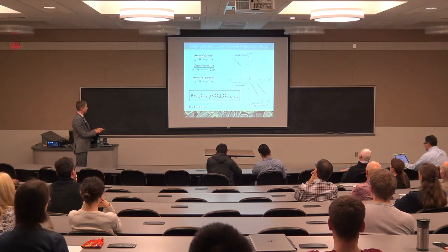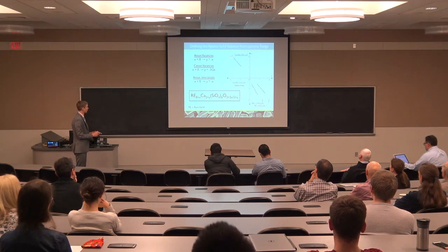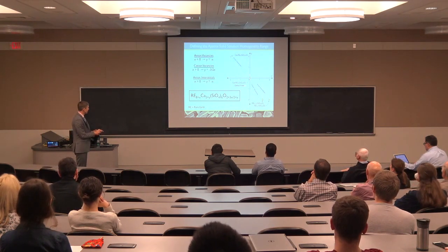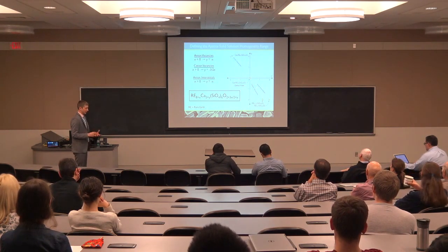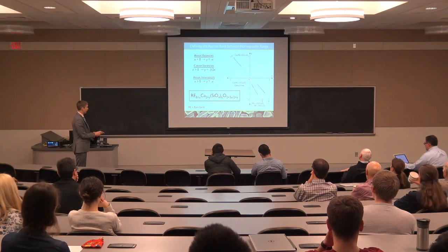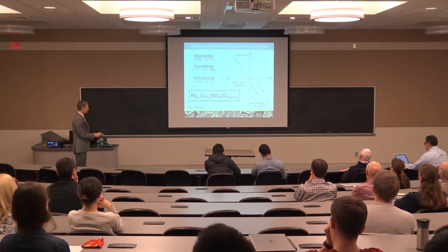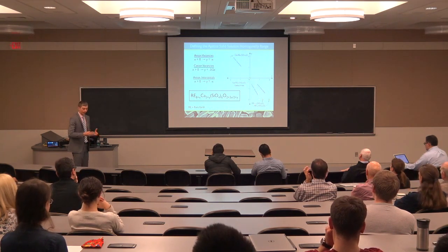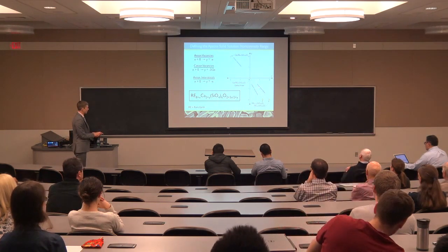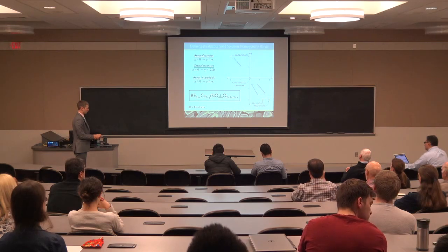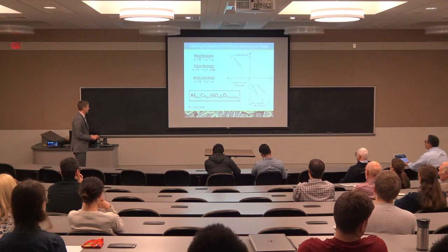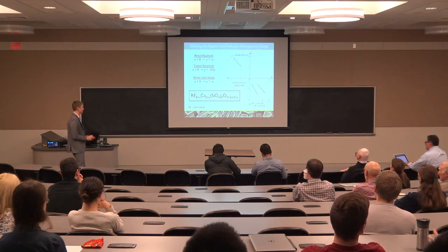If we go in this direction, which involves putting more calcium in, we have to introduce anion vacancies and anion sites to maintain charge balance in the structure. If we go in this direction, which is taking calcium out of the system, putting more of the rare earth into the system, we can follow two paths. One might be by incorporating cation vacancies, leaving some of the cation sites vacant to balance the charges we remove calcium. Or there's been some suggestion maybe you could put anion interstitials in, stuff additional oxygens into the center of that column of the cation sites to also balance charge.